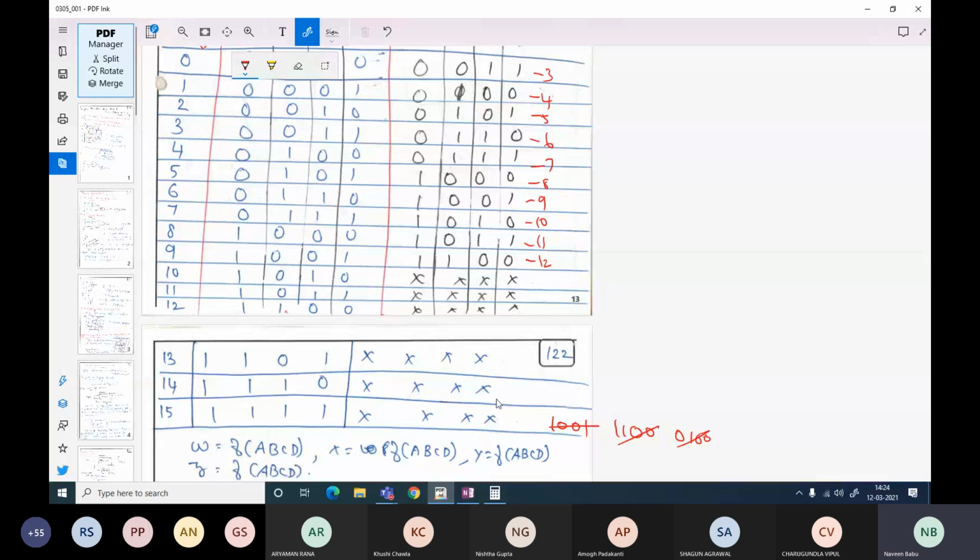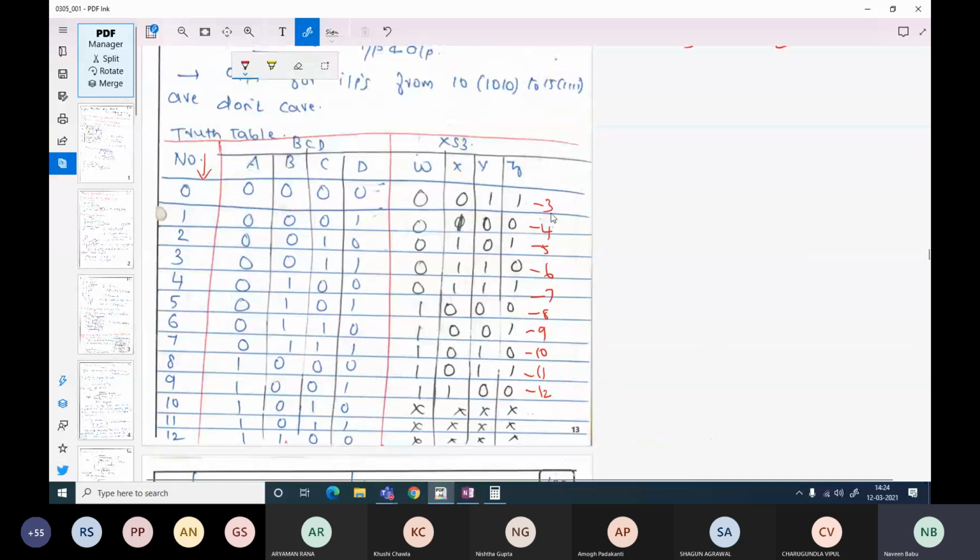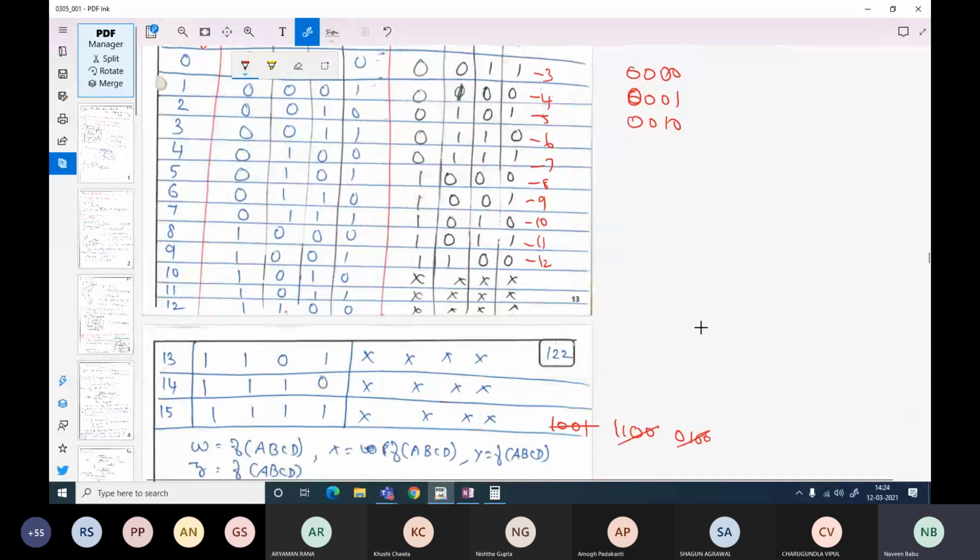As a good design engineer, you should not have such random displays for different answers. So you can decide what to do with the inputs we have not used here. Instead of these don't cares, you can create 0000s and state in your manual that whenever an invalid input is pressed, you will get an output of 0. This is how proper design engineers must think.